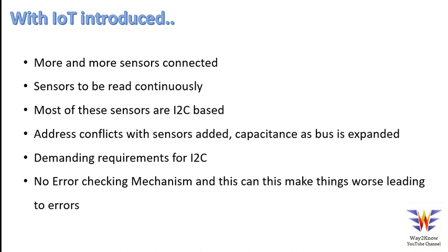Now the same I2C interface is used across different devices, whether it be any PROM, simply PROM, or any devices for which configuration is required, like LCD backlight control, or the accelerometer, gyroscope, and all these which we use, and then the battery chargers, fuel gauges.